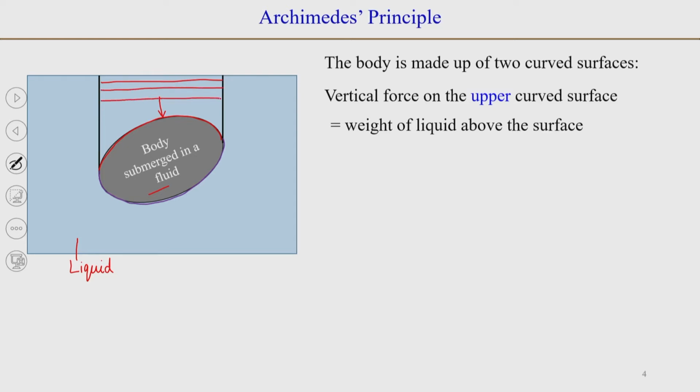Let us hatch this volume by horizontal lines. Okay. So, the volume of liquid that is above this curved surface will give the force, pointing downwards, on this